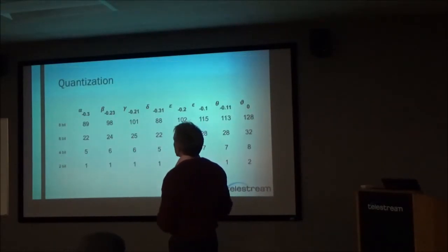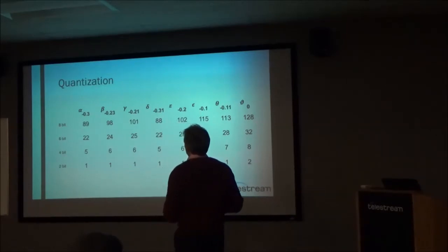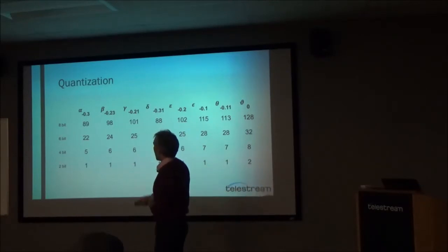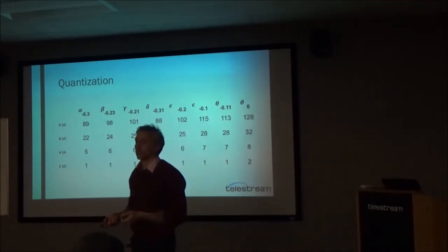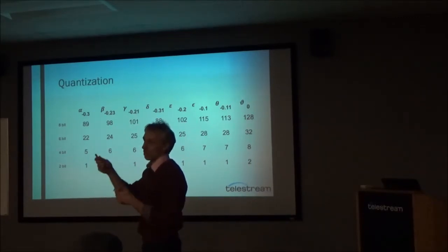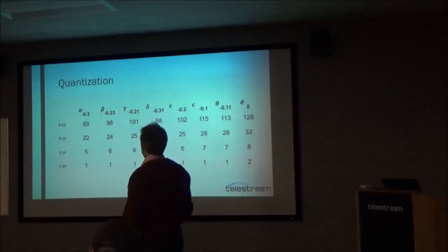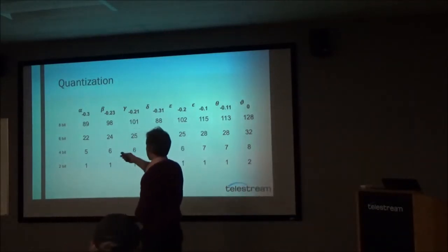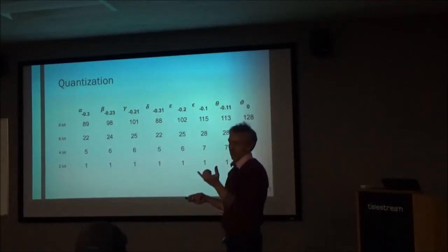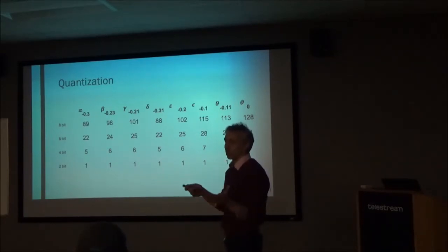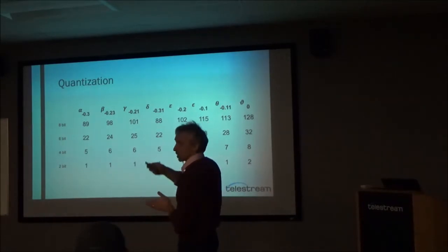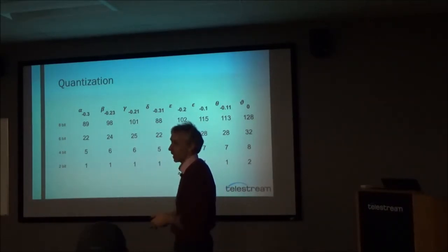And that's where this idea of quantization comes from. If I wanted to send these numbers, these are my coefficients for alpha, beta, gamma, etc., I could decide how many bits I wanted to use to actually send that number. And the more bits I use, the more precision I have, and the better that particular pattern is represented in the bit stream. So if I want to use 8 bits, I use these numbers; 6 bits, 4 bits, 2 bits, these numbers. And we really do that. We take the patterns that are all very solid, and we use a lot of bits for that information, but we quantize, or use fewer bits, to represent the numbers for the patterns that have a lot more changes in them.